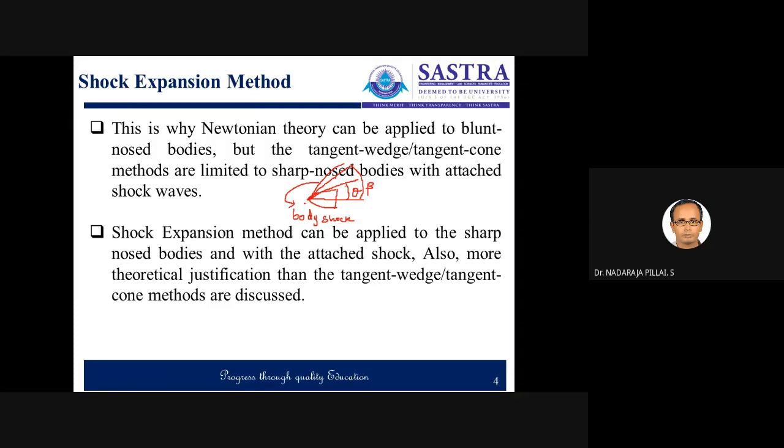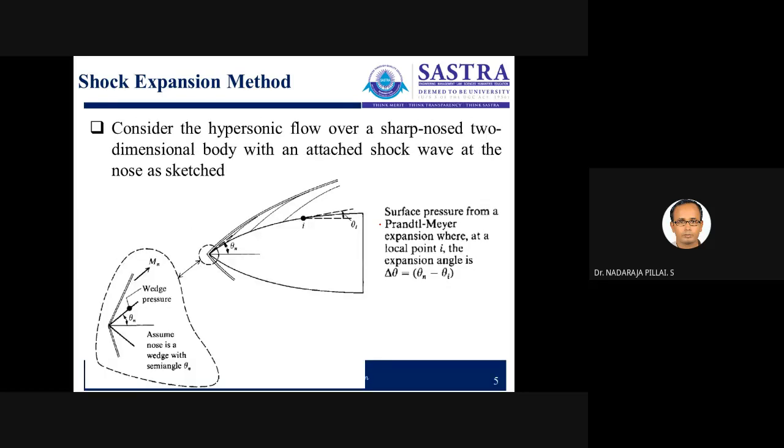Now, the shock expansion method can be applied to a sharp-nosed body with an attached shock. In the case of the tangent wedge and tangent cone methods, we don't have any theoretical justification, but in the shock expansion method, we can have the theoretical justification. So let us look into the shock expansion method.